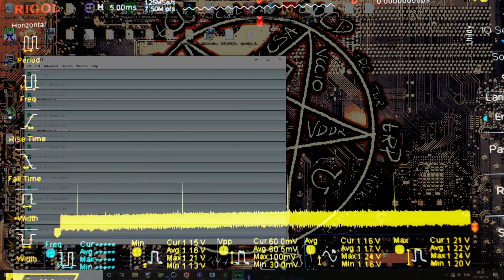I kind of want to take the board apart and see if I can figure out what the VCC Sense versus Socket Sense circuitry is. Because theoretically, the obvious answer to why this would be happening is the Super I/O just gets connected in parallel with the voltage regulator, which seems like a horrible idea.